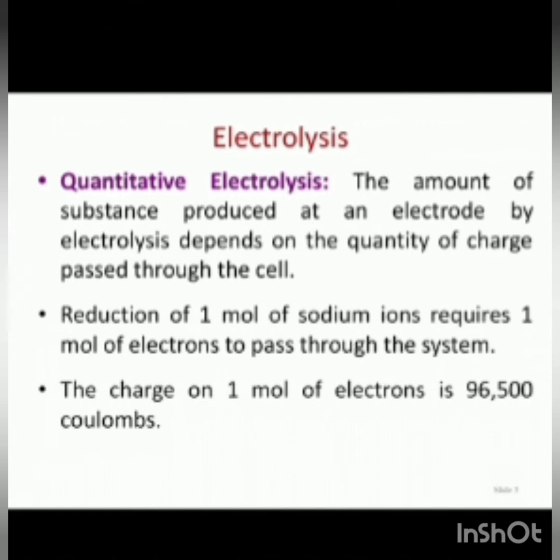The negative sulfate ions move to the electrode connected with the positive terminal of the battery, where they give up their extra electrons and become sulfate radicals. Since sulfate cannot exist in an electrically neutral state, it will attack the metallic positive electrode, forming a metallic sulfate, which will again dissolve in water.